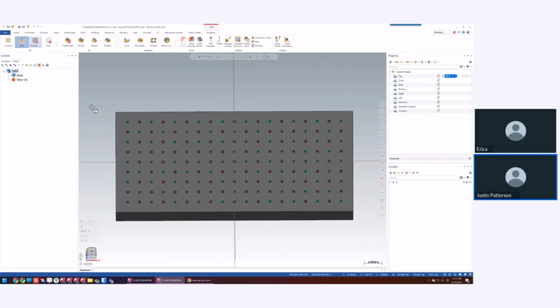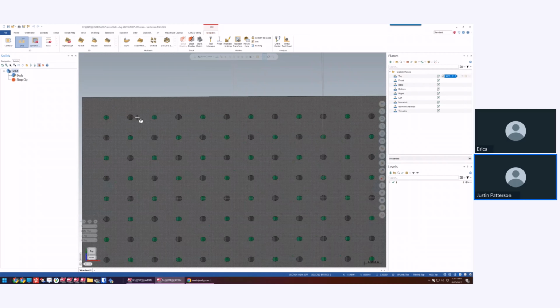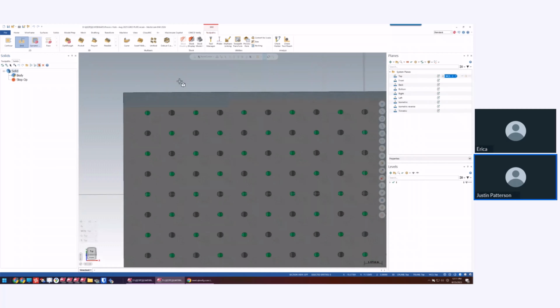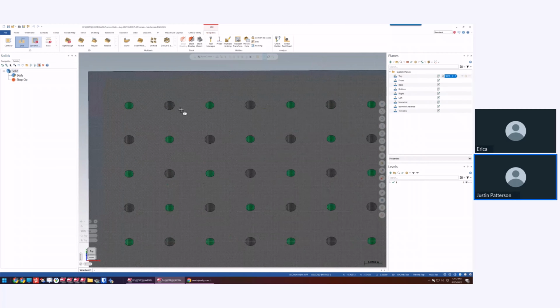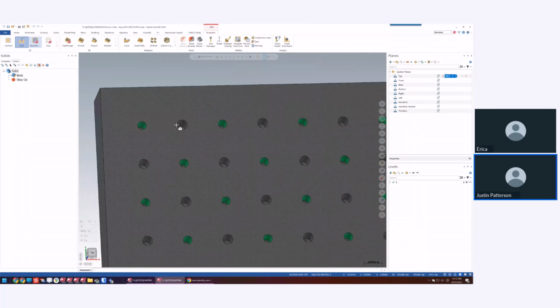But I kind of did it a little bit like that when I come in here to my dowel pins, because you mold and tool and die makers taught me this. I never knew that, but to do a true dowel pin hole, you want to drill it fairly undersized, interpolate it within like 14 thousandths, and then you can ream it. Well, guess what? I have all that set throughout my template here.